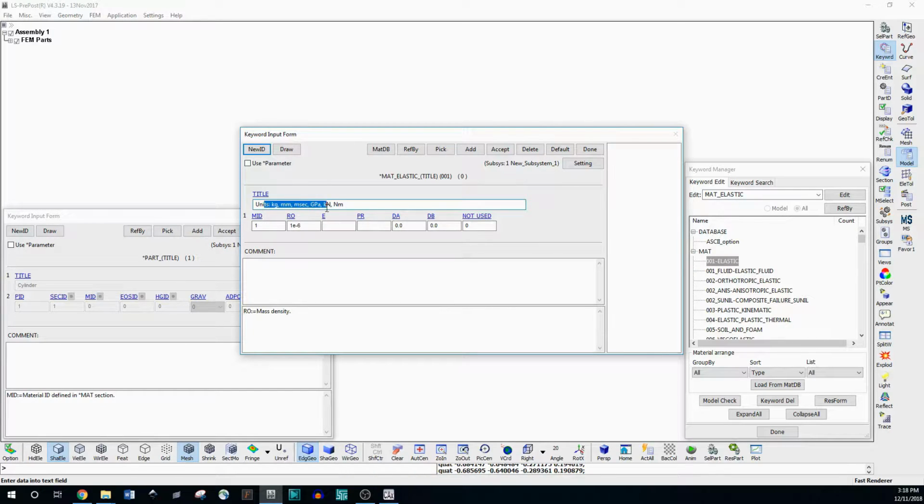And if you keep these consistent, it's going to define the rest of the units for you, if that makes any sense. But for now, density is going to be density of water. So we're going to define the elastic modulus as 0.1 or something similar to rubber. If you're looking for examples, you can just Google it and find out whatever the material is that you're looking for. That's the benefit of using a mat elastic, because everything in here you can actually find by just Googling it.